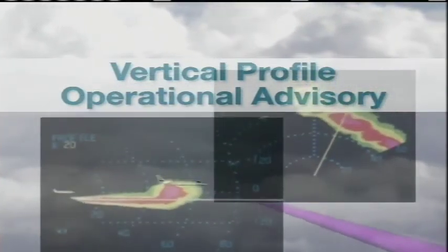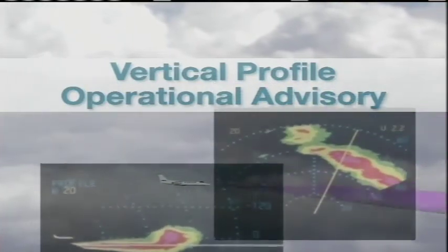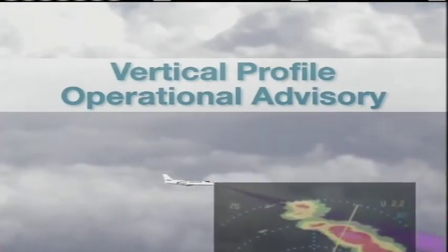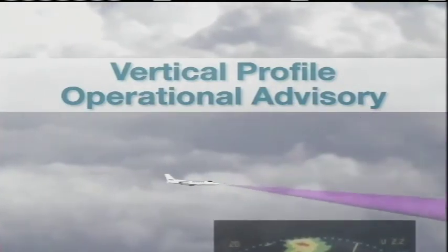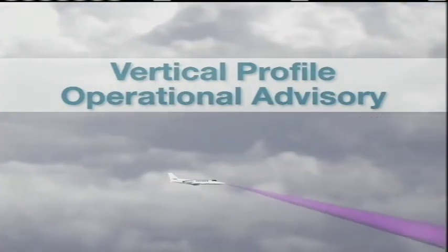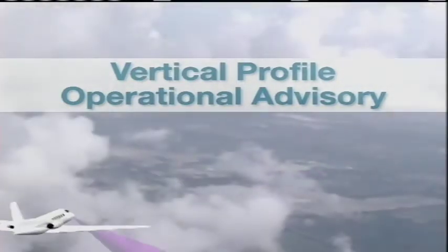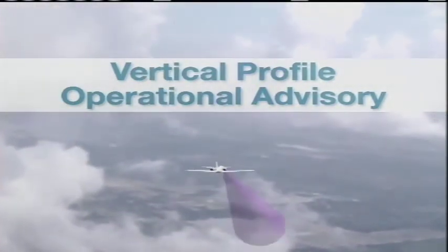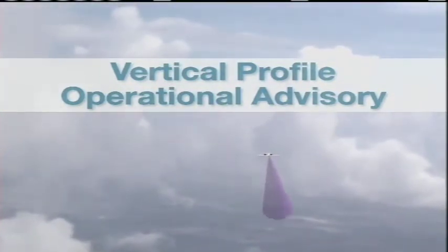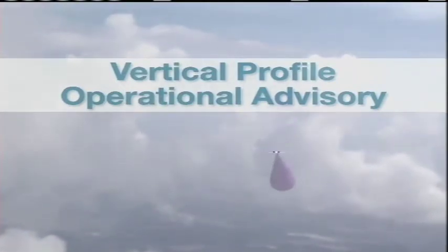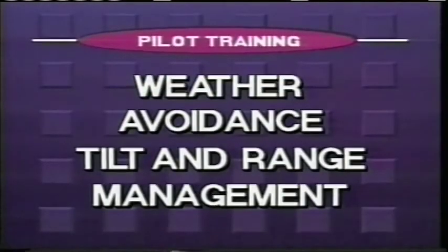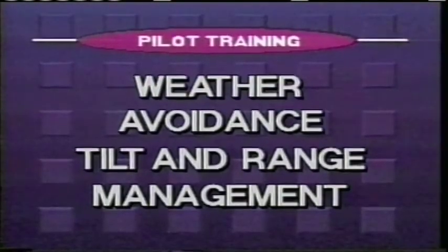Note, the NavMap mode is disabled during vertical profile operation. Also note, vertical profile is most useful in the wings level operation mode. During a turn, constant adjustment of the track button would be required to view the same area of a given cell. Roll stabilization is not functional during vertical profile operation. Therefore, during a roll, the vertical profile slice angle equals the bank angle of the aircraft, providing a skewed vertical profile display.